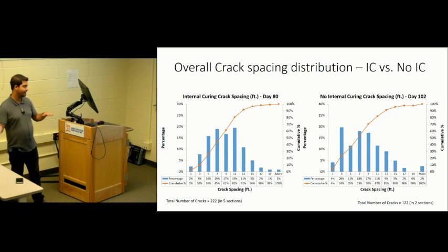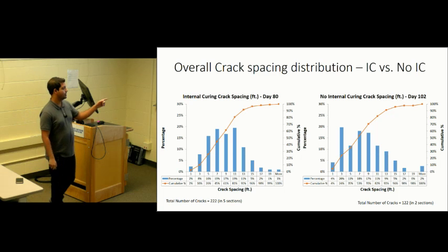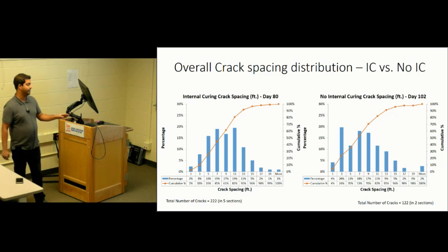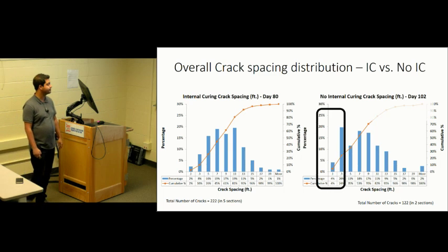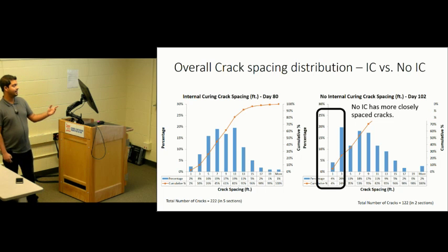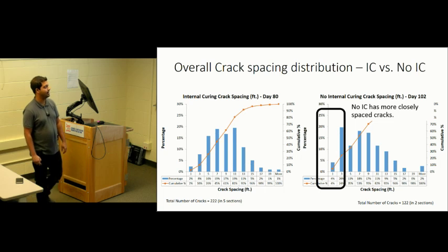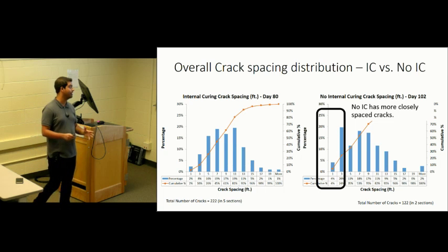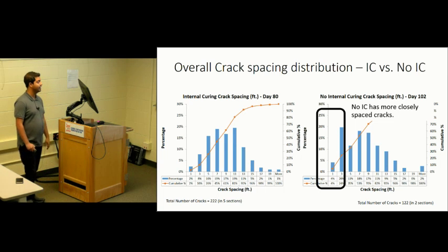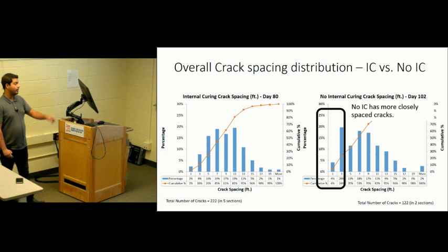They are slightly apart, like 1 mile apart. So we have different days for which we have done the crack spacing and compared the cracks. We can see that for the non-internally cured section, the cracks are more closely spaced than in the internally cured section for early age.